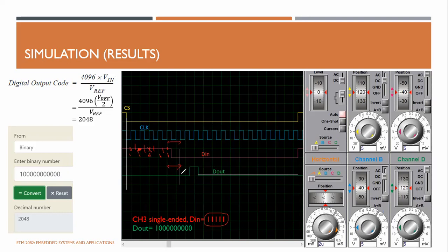At the end of this period, it starts with this null bit, which is 0, and then on every clock falling edge, it is sending data. You can count the clock periods: this is 1 clock period, and this is 1, and this is 0. Likewise, all together up to this point, it will be 11 zeros. So that is this number. And again, I have deselected my chip from the signal generator. This is the pulse that I have generated, considering the timing.